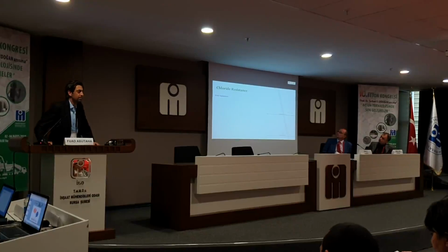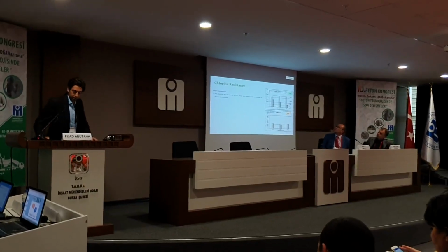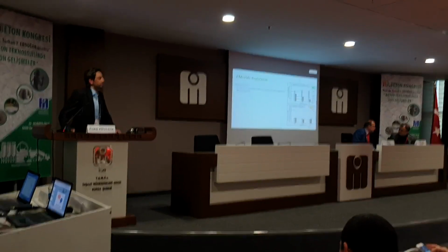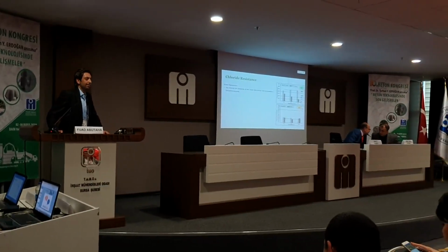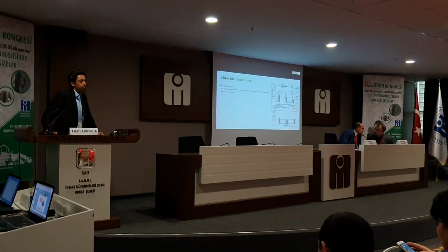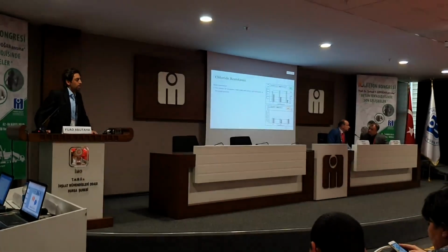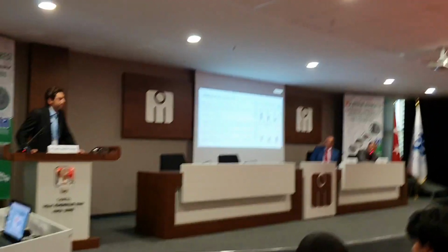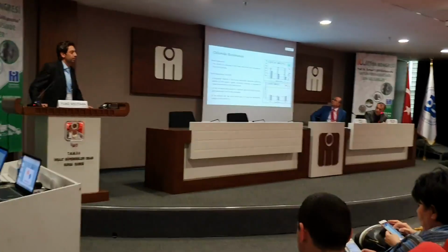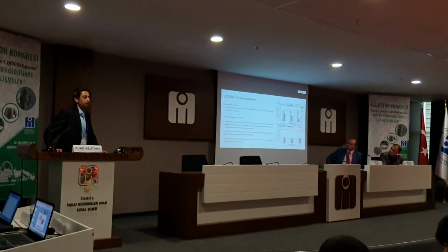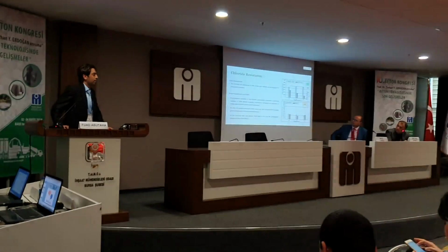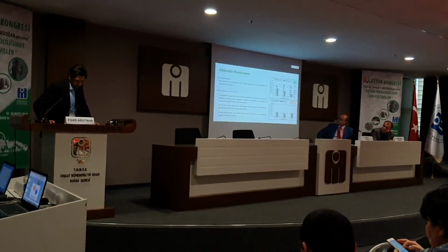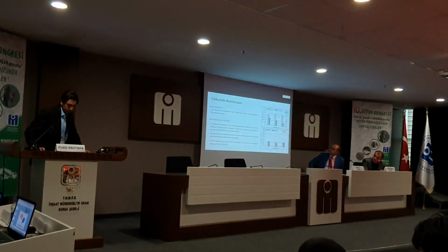For the chloride resistance, the rapid chloride permeability test doesn't show any difference between the mixes with POC coarse aggregate. It was comparable with the control concrete, but after incorporating the POC powder as a filler material, there is a significant reduction in the chloride ion penetration.